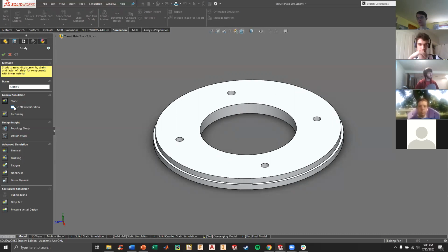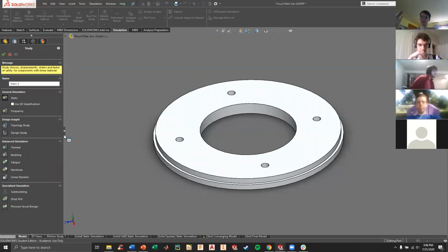So essentially what that means, with the linear static simulation, it uses only that slope of the stress strain curve and doesn't actually use anything past the yield point of the material. And then also static means that as the part deforms, it doesn't recalculate any of the interactions between the parts. So if you have a model that's going to deform a lot, usually like a plastic thing, you'll want to do a nonlinear study, a nonlinear dynamics study. And then you can get into more interesting interactions. But for us, mostly using aluminum, you can get pretty good results from static simulation.